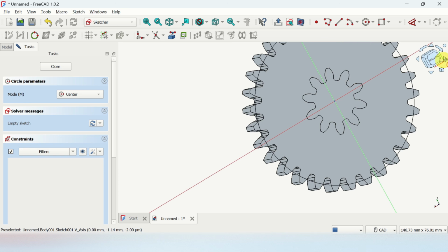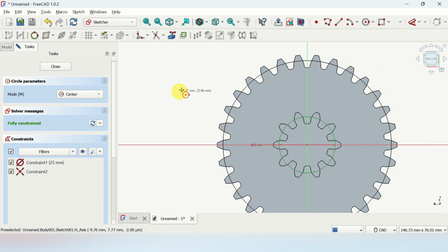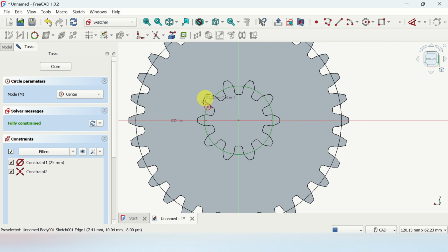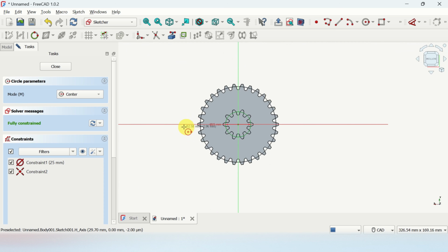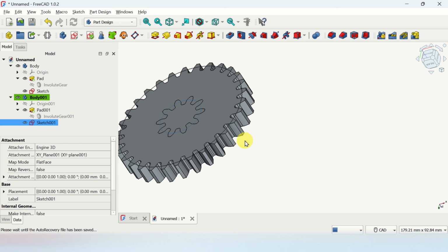Here it is. Let me just click here on bottom, click here, and then let's specify this to be 25, and that's it. And now you can clearly see over here that everything is designed as it should, since this circle or the pitch circle is approximately in the middle between the top and bottom surface. Good. Do the right click, click close to exit, and let's continue further.